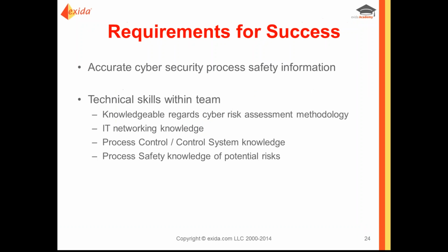So if we go back and look at the overall requirements for success in your cyber analysis, you need to have accurate information about your process to start with. Your zone and conduit drawings need to be correct.